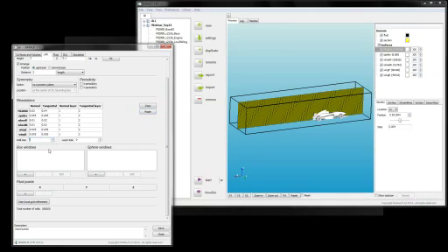Also, I'm going to grow 2 layers from the walls, and then this layer size, this other parameter, is a parameter for how many layers of cells are contained within basically every category of refinement as you go from the finest to the coarsest grid. I'm going to put 2 in that as well.